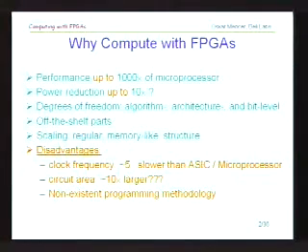Disadvantages, offhand, the first thing that you see when using FPGAs is that the latency is going to be slower. So you're running at roughly 5 times less clock frequency. And taking this particular circuit and putting it on an FPGA, you'll also realize that it's about 10 times larger. The ballpark figure is that FPGAs today would use about 80% of their area to allow all the flexible interconnect that they provide. And this is basically wasted area. So if you have a circuit that you put in there, 80% goes for the flexibility that you get with the device.